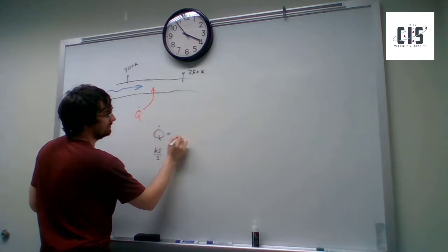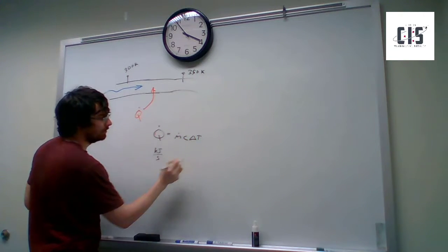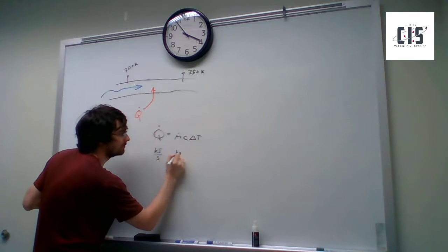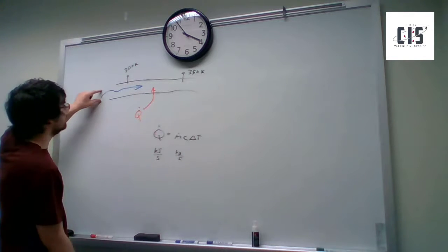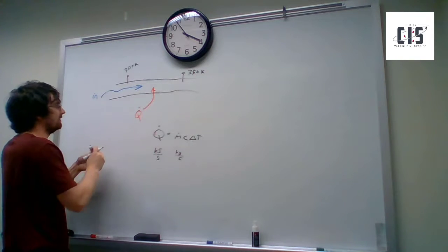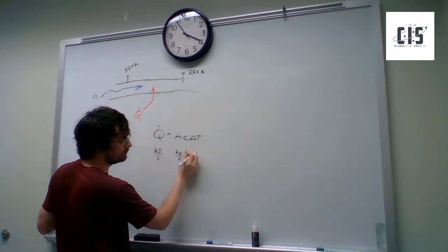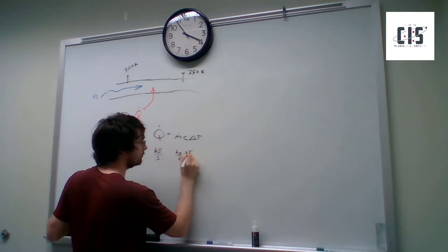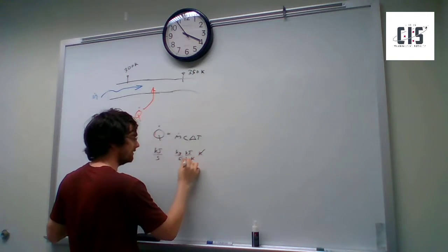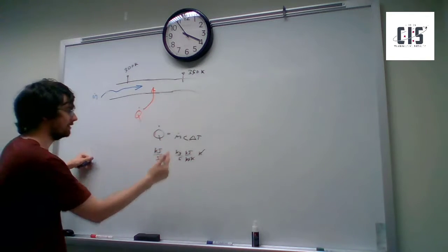So that's equal to the mass flow rate times the C times the dT. So exactly the same thing, it's just the mass is in kilograms per second. And you need to know the mass flow rate here for that to work. So mass flow rate, heat capacity, excuse me, kilojoules per kilogram K, and then K. Those cancel out, kilojoules per second, perfect.